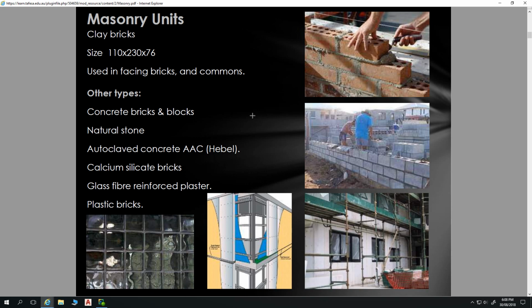It was important for me to remember because I did a lot of detailing up of places from photographs. When the New South Wales office was busy, they'd be taking photographs of buildings that needed detailing up for repair and reinstatement, and then sending them over to me, sometimes without measurements. So I'd have to count the bricks to get ceiling heights, sizes of windows and all that sort of thing. It's something I found myself doing a fair bit, so you have to learn your brickwork dimensioning very well.